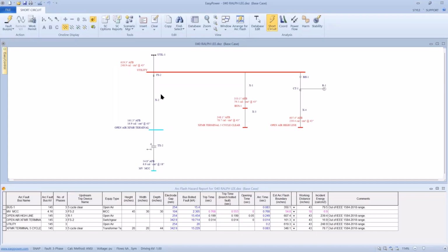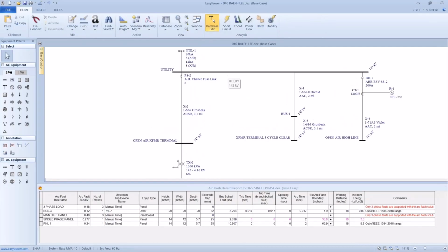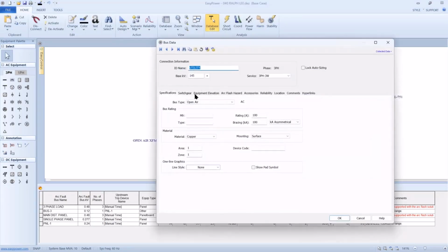Now, on the other hand, if we look at the applications where most high voltage applies to a bus that's open air, then the concern turns to, well, we're talking about a termination or a phase separation that's considerably more than 350 millimeters, and it could be in terms of feet as far as the separation between the phases. So the concern is more single line to ground faults, and that's where we're going to apply next.